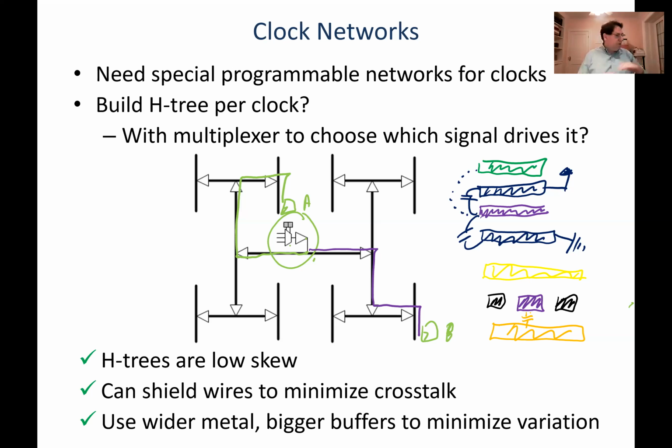There are a lot of different wires crossing it, but that's actually good because if they're all doing different things, some of them are transitioning, some of them aren't transitioning at the same time, some are transitioning up, some are transitioning down, they tend to cancel out. So the capacitance to these wires above and below is much less of an issue because first, the capacitance is smaller. This actually is further apart. And secondly, there's a whole bunch of little capacitances to different wires. And if you add up, okay, what's the net effect of those wires kind of transitioning at random? It doesn't add up to nearly as much. Does that make sense?